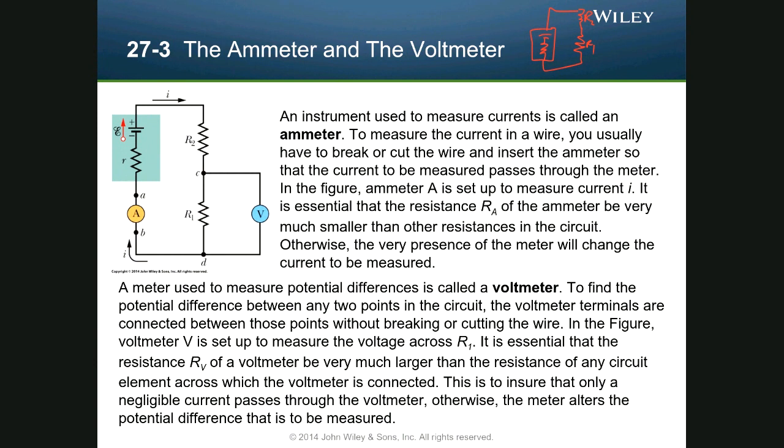It's really pretty easy. If you can imagine these two pens, if the resistance is my head, and you have a voltmeter on the other end of these pens, I don't want to get ink on my head. You just put the probes on the circuit and you measure it. These dots here, you kind of make it part of the circuit, but not really. You'll understand why this works, because when things are in parallel, the voltage in each branch will be the same. So you get the voltage here across the resistor, it'll give you the same voltage here.